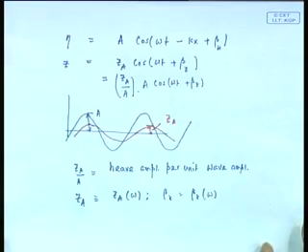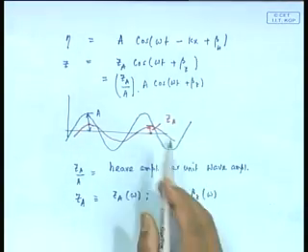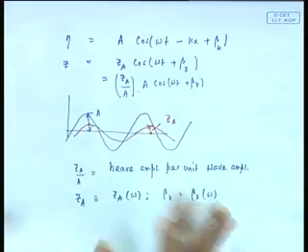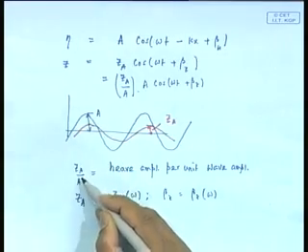Explaining on, right. See what is happening now. Let us take one particular wave of some length, say 100 meter long wave. I put my ship there, it responds, say wave height is 1 meter for that. So, it will go up by say 2 meter, ZA is 2 meter. Now, if I have 3 meter, then it will be 6 meter, because in that particular wave of given frequency, my response is linear, because as I said, 2 times a 1 meter wave is equal to a 2 meter wave. Okay. So, ZA by A is constant, that we know. My point here was to say that ZA is a function of omega.